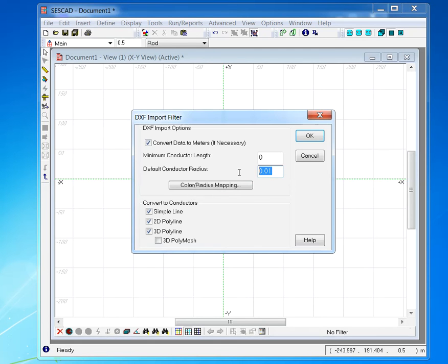It's important to change this one here, otherwise you will have to change it later, and it's easier to change from here. But before that, we want to make sure our system of units is British. So let's close this before importing it.